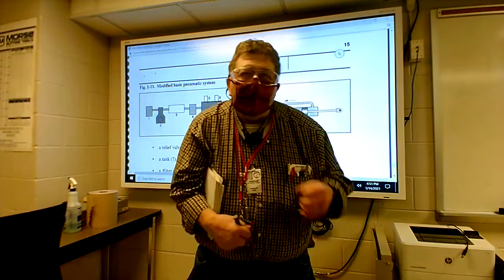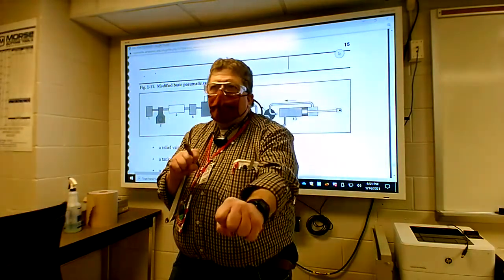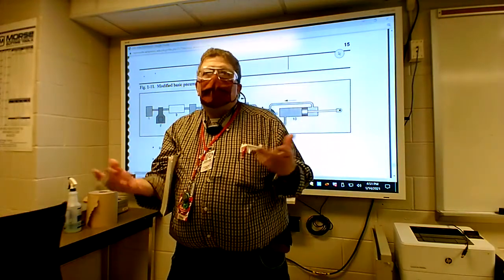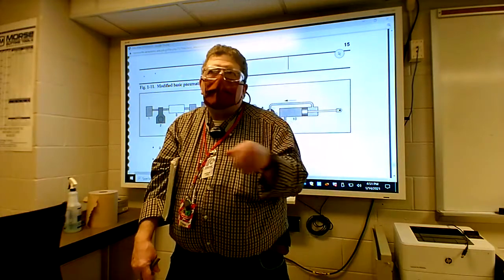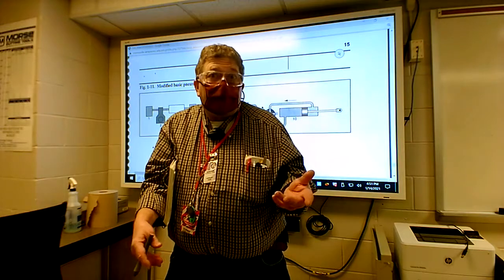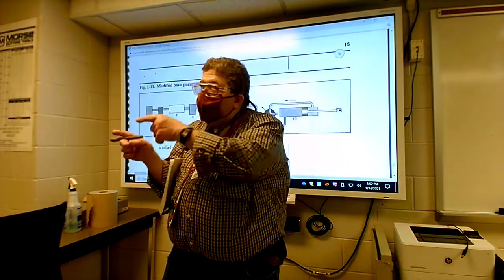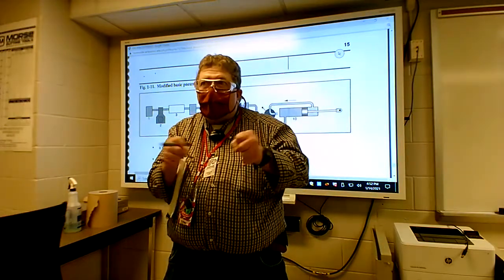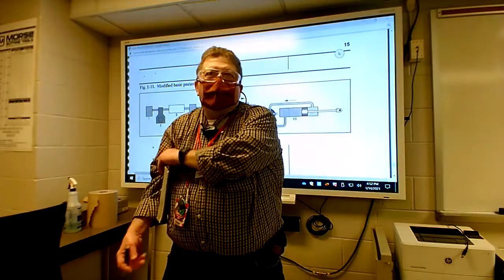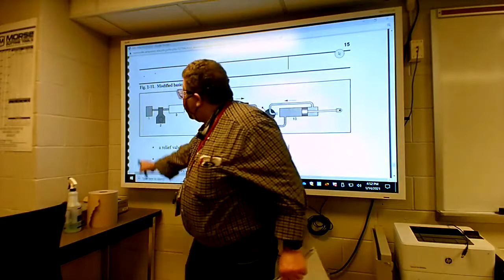It's the same thing with an air compressor. Could you imagine on the intake stroke, you pull in a certain amount of air and then you shove it through the piston? You've got dirty air. What's going to happen? The piston, after a while, you're going to have problems. The seals are going to be breaking down. Yeah, they'll rot out. And then you'll be pushing contaminants through the system. Then they're going to get into your machine that's got small little valves ticking and talking going on, and you're going to have solenoid valves on the machine clogging up, things like that. It's not good.